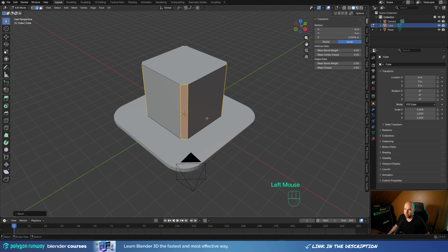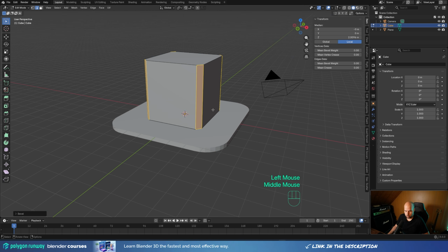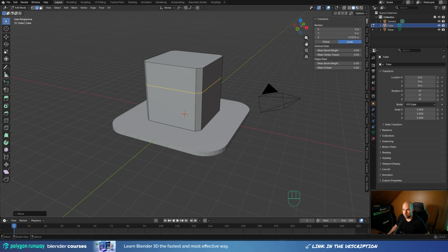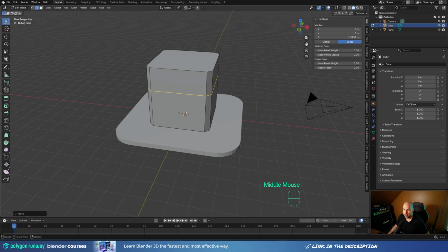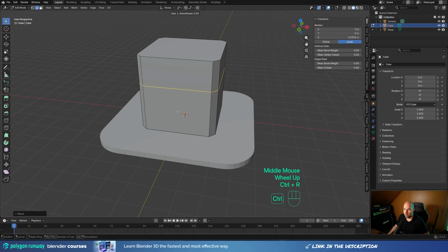like this. And now I want to add some more geometry, so press Ctrl R and add a loop cut right here, because I want to create that opening for our ramen shop. And now I will need some more edges on the sides here, and the easiest way to do that is to press Ctrl R to just add a new edge right here. You will see if you go this way, it will try to create a loop cut there, but here this is what I want to do. So let's left click and right click to release in place.